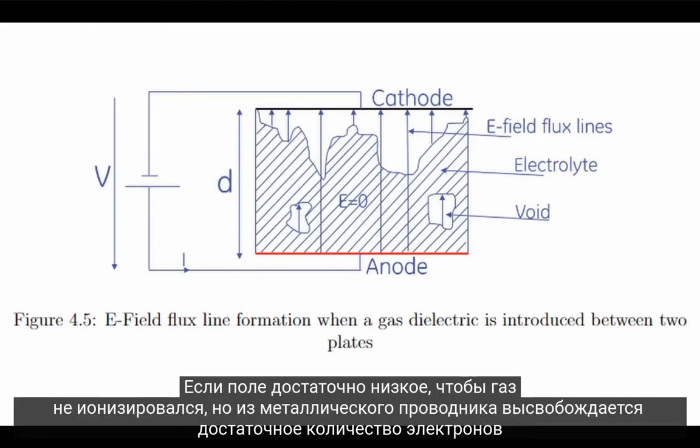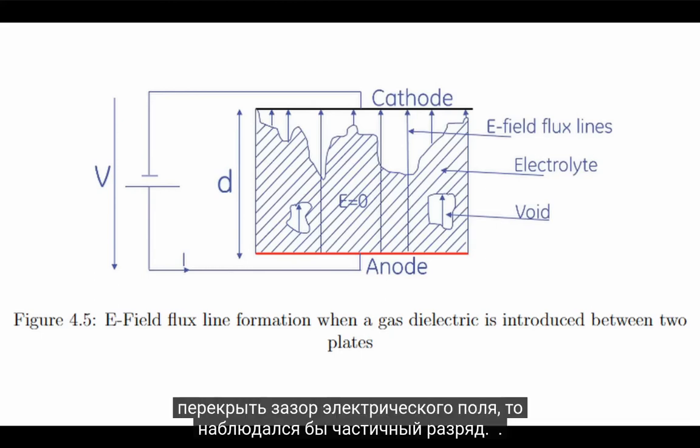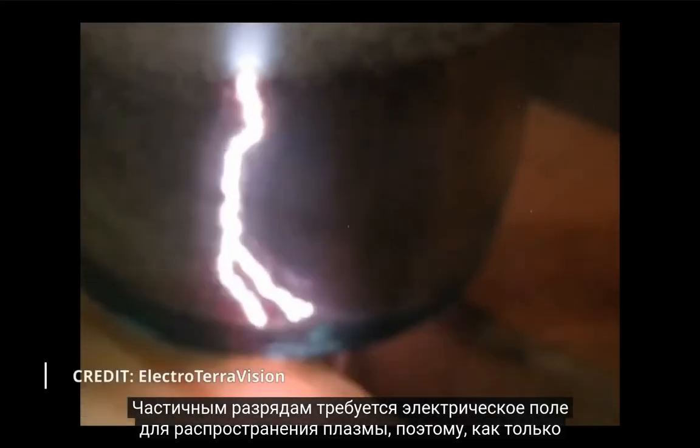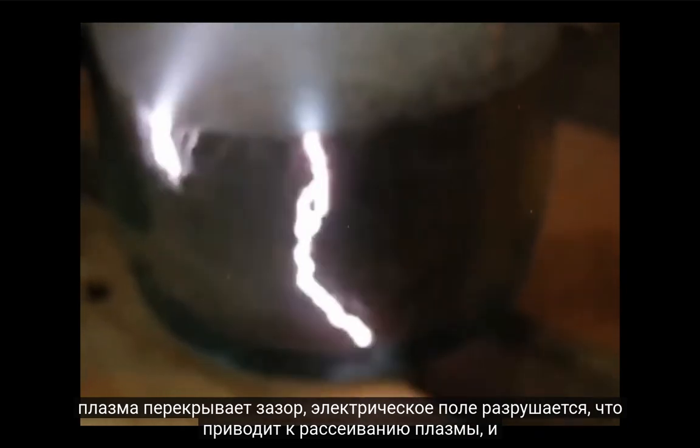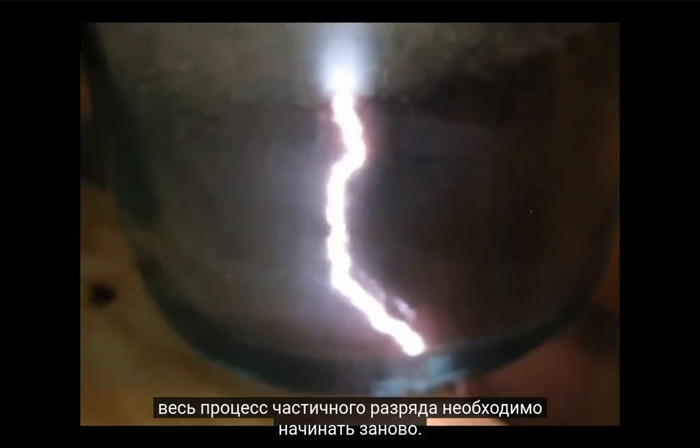Partial discharges require an electric field for the plasma to propagate, so once the plasma has bridged the gap, the electric field collapses, resulting in the plasma dispersing, and the whole partial discharge process would need to start over. A partial discharge is not visible as it occurs inside a dielectric material.